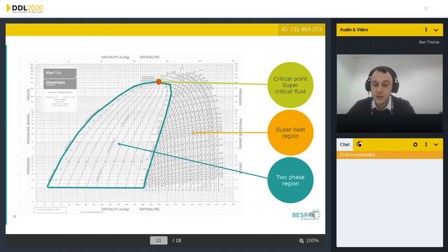So I think now we've got some interesting science to come. Fundamental to our whole approach is this pressure enthalpy chart, which varies with each different propellant type. And we can represent this graph by a number of polynomials which describe the properties of the individual propellant. And we can see three regions there. There's the two-phase region in the middle, which I'll talk about on the next slide. There's the superheat region on the right-hand side. In that region, if you add heat, you just get a change in temperature. There's purely just vapor there.